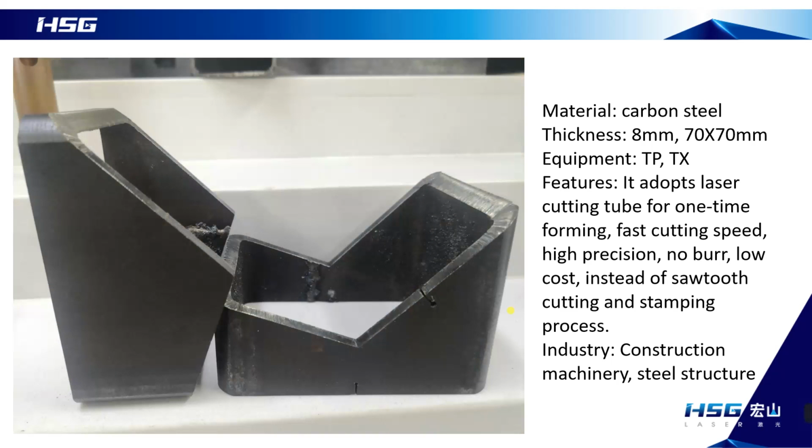What industry is bevel cutting mainly used in? Welding. When we normally cut, the edge is straight and vertical, so the welding can only do line to line. For example, the outside line and the outside line coincide. But with the bevel cutting process, it can do a joint between the surfaces. Relatively speaking, its strength will be higher.